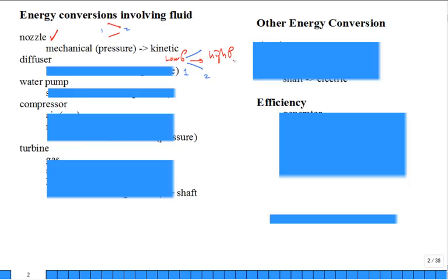Most of the time, flow goes from high pressure to low in a duct or a pipe or some system like that. But there are cases where you have flow going from a low pressure to high pressure. Does flow like to go from low to high pressure? No, it's like pushing a rope. If you try to push a rope, what's it trying to do? Curl up. You can't push a rope very well. You could pull a rope well. Fluid likes to go from high pressure to low pressure. That's like pulling a rope, but to go the opposite in a diffuser.